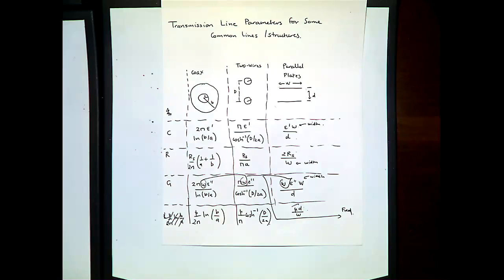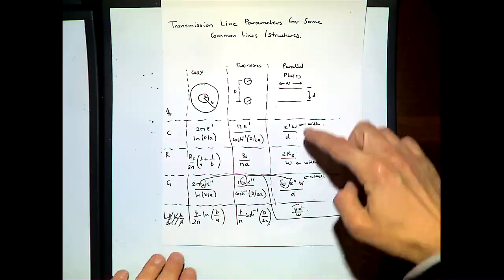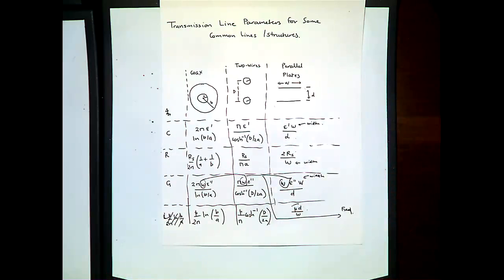Because if you think about it, at the self-resonant frequency the impedance goes to infinity, but it also means that you now start having a significant portion of inductance relative to your capacitance. So essentially what I'm trying to say here is there are these fundamental relationships, and it's important for you to be familiar with them.